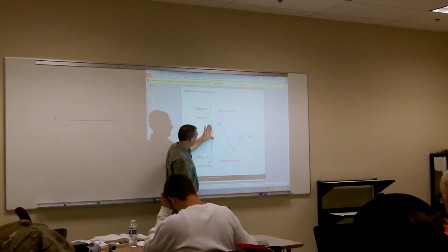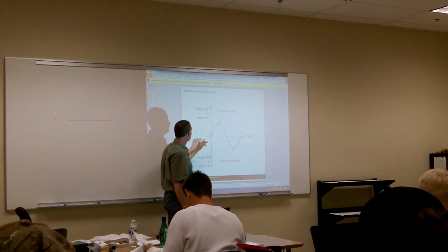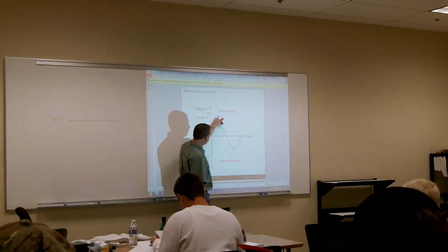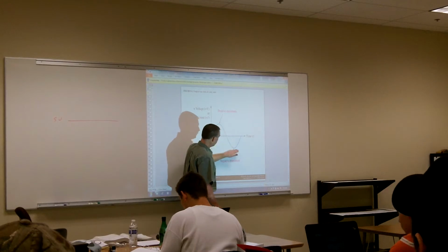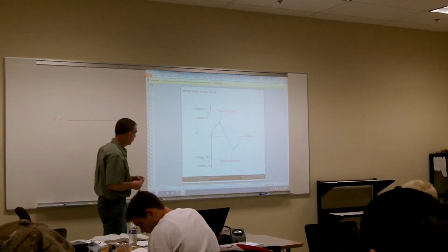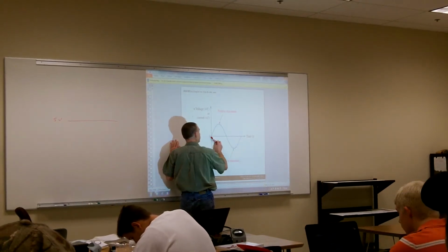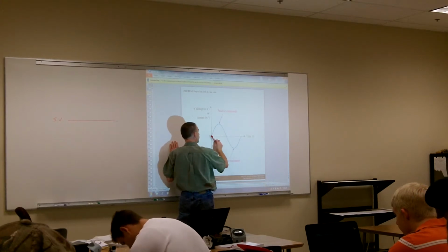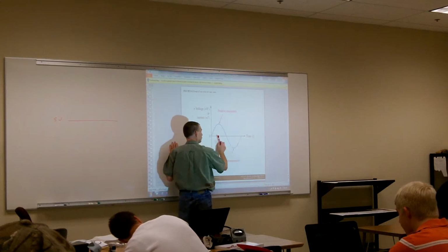When we're working with AC, we have a signal that's varying our voltage. It's going up to a positive voltage, and then it's crossing our 0 volts reference, and then it's going down negative, and it's changing directions as it's doing that. So either our voltage or our current is going to have polarity. One complete cycle is from the time it starts to the time it starts to repeat itself.